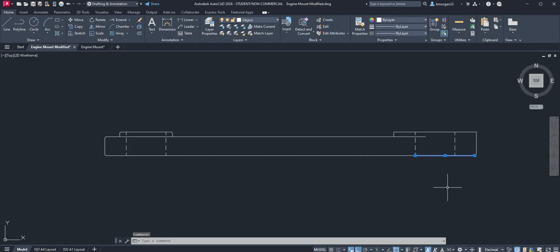See this? Okay, and you're gonna press the delete key on your keyboard if you want to do it directly. You can also do erase, which is under Home, under the modify panel, and there is a little pencil button right there, and you can use one of them to delete that line. I just press my delete key on my keyboard to delete the line I have just selected. Okay, so it will go away.